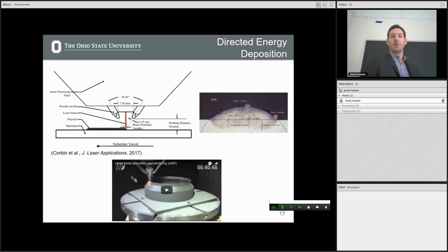So here's an example of the metal substrate. You have the powder, which is then formed here. And you can also see what's called the heat affected zone. This is what saw the laser power, is melted and therefore forever changed directly under here. So you actually see the change in metal structure went into the base substrate as well.